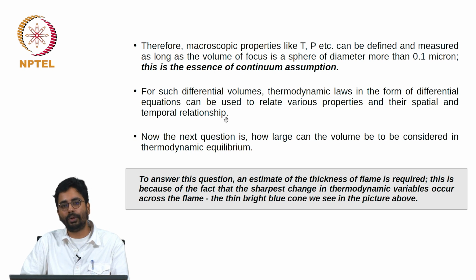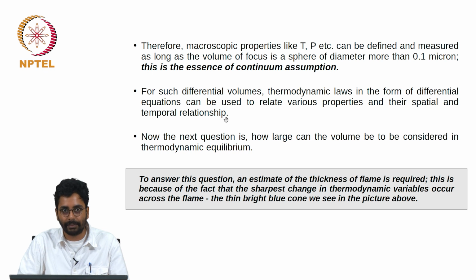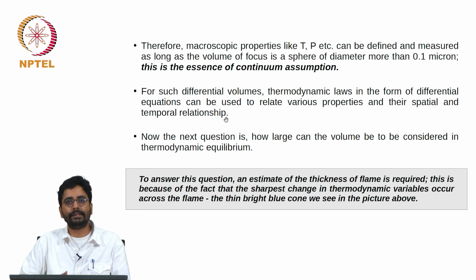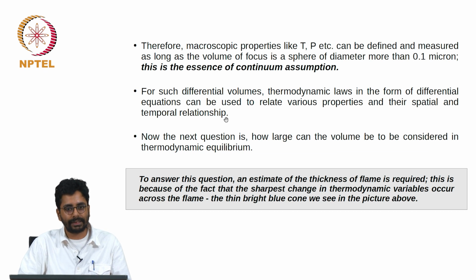Now we can move on to the next limit, which is how large can the volume be to be considered in thermodynamic equilibrium. But to answer this question, we need to have some estimate of a length scale of relevance to flames, which we will call the thickness of the flame. This is because the sharpest change in thermodynamic variables occurs across the flame.